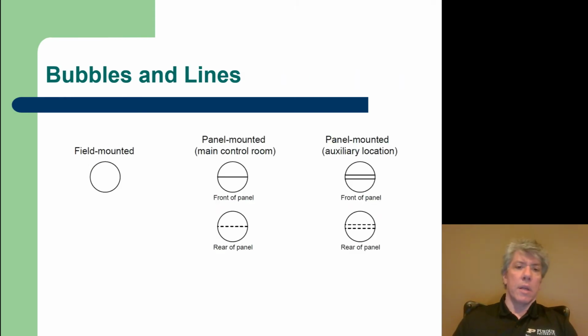So you'll notice that there are bubbles and lines in these diagrams, and many of the aspects of process flow diagrams and piping and instrumentation diagrams, as well as some of the other diagrams we're going to see, is actually controlled by the Instrumentation Systems Automation Society, also known as ISA. As a standards organization type body, the standard does change from time to time, and so you'll see changes in it, but generally it remains about the same because it serves an important purpose of standardizing communication about standard sorts of things, standard equipment, and often standard processes.